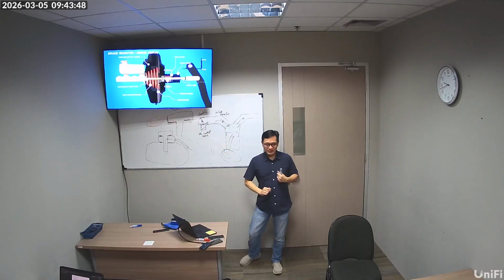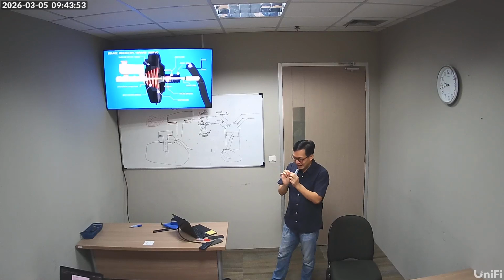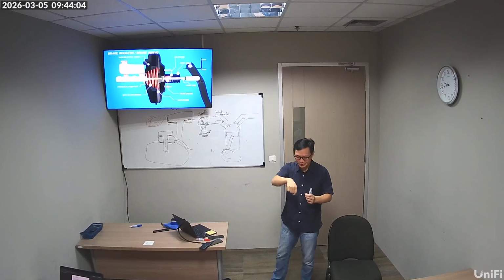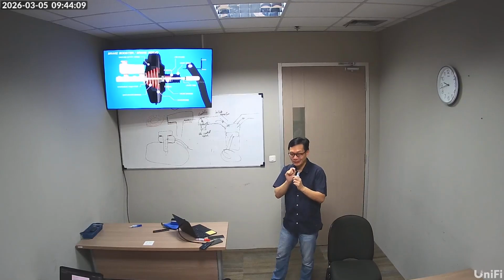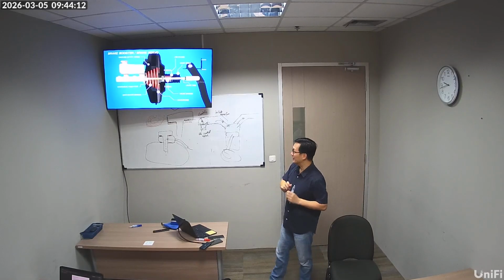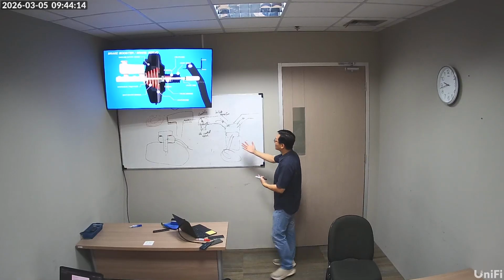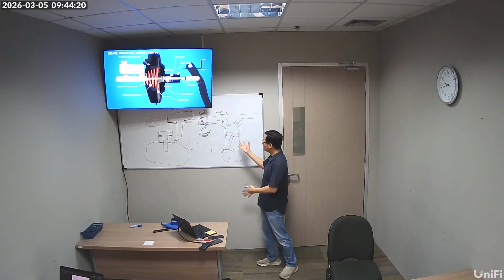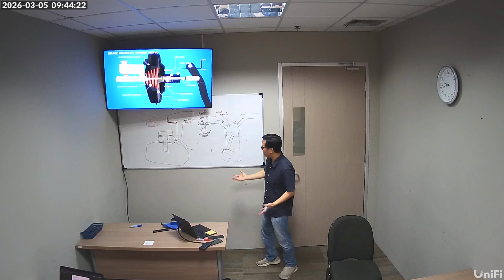However, think about an idle situation, or when your throttle is all the way closed. Think about a very powerful pump sucking in a tiny straw, and the straw is really tiny. Ever tried to sip your coffee through the stir? It's not meant to be a straw, it's a stir, but there is a tiny hole going through. If you try that, it's a lot of vacuum. And that's what our engine is doing when you release the throttle. Your engine becomes a vacuum pump, essentially.